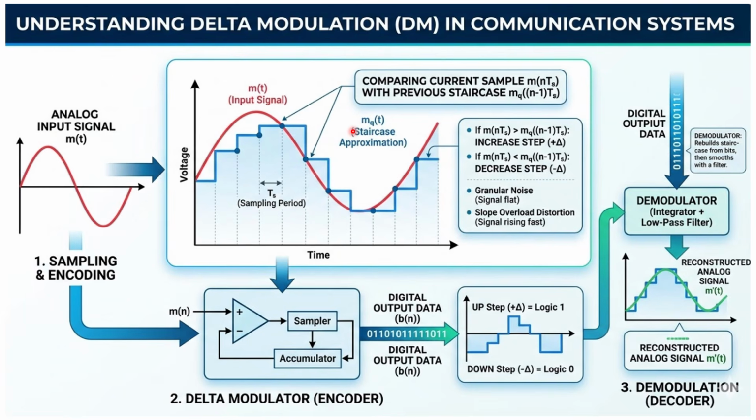So delta modulation is one special case of your DPCM. There is not much difference. Here also we are going to send only the difference information. We compare the information with the previous message, and then we send the difference in between. Finally, we encode the information and send it to the channel. So that is the final message information corresponding to this message.